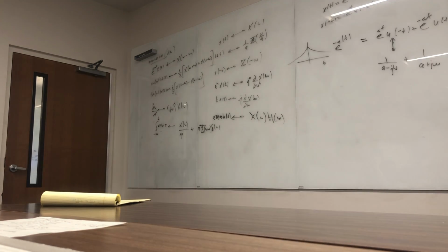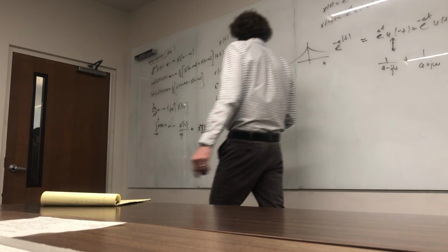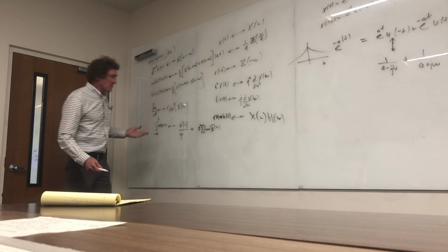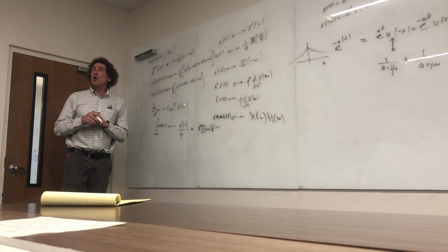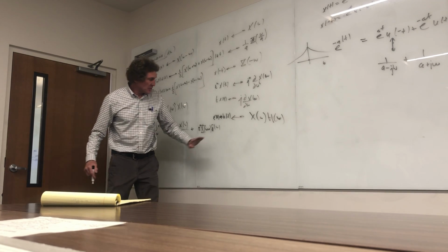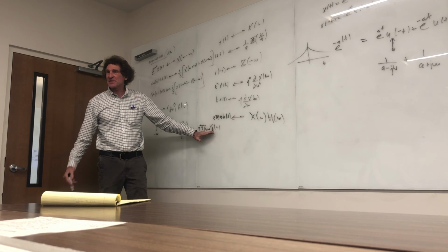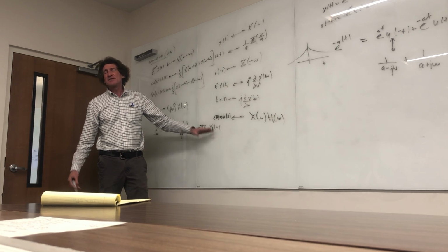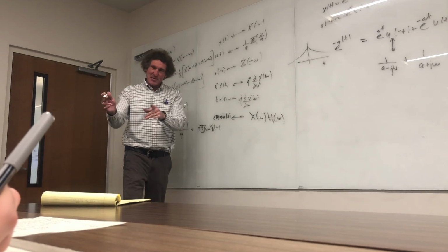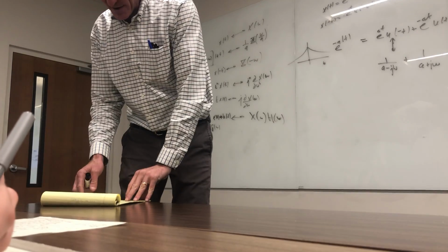Does this have an average power that's 0? 1 is DC, it's on forever. It's got an average power that's non-zero. Do you follow me on that? And it has some amount of power that's there no matter what time period you average it over, all right? Here, if you have a functional form x of t that has a non-zero average power, then you're going to get this. At omega equals 0, you're going to get that value. And that's just the DC power. Think of it that way. It's associated with DC power, though it's not actually. We're about to get to that, by the way.